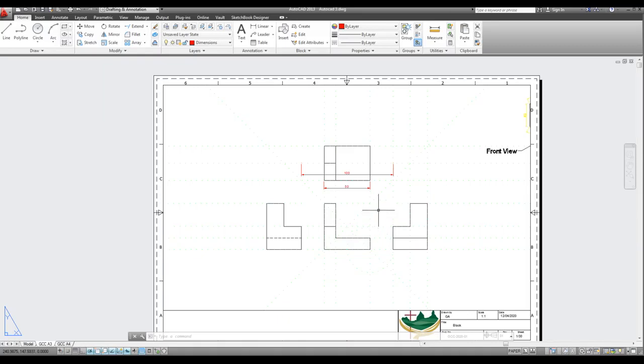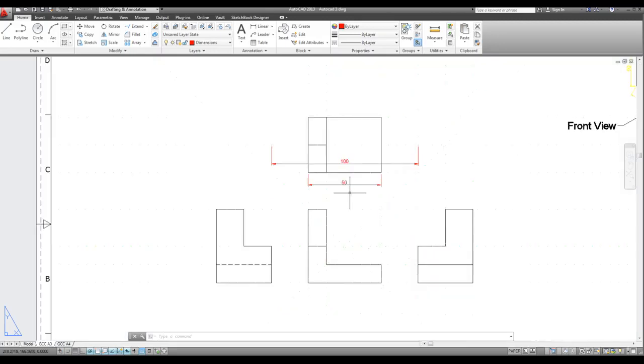Your customer might have told you, I want it 100 millimeters long. You do a drawing like this and it gets sent out to the workshop, it'll get made half the size. You would need to be aware of that when you saw it. If you scale it down, and when you go to dimension, oh, that's not the right size, there's something wrong here. The issue is that the dimension is not associated to the actual model space.